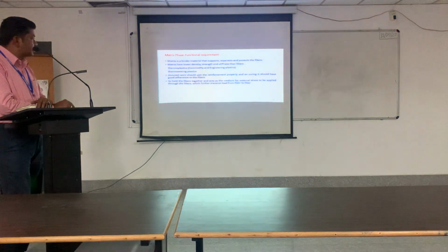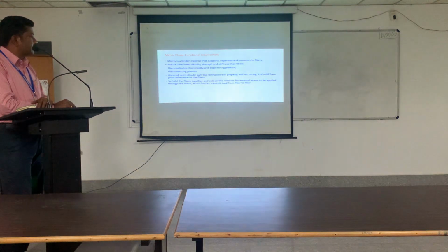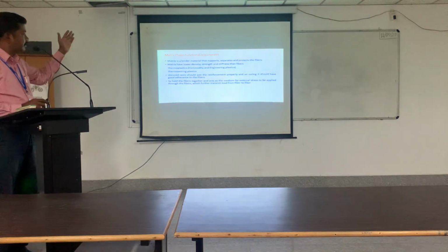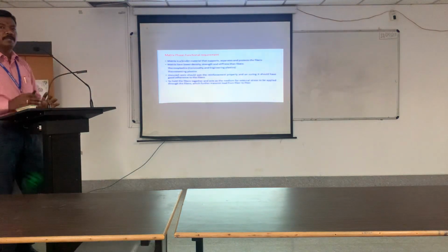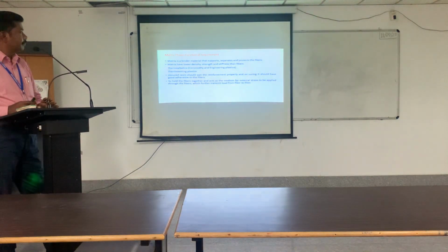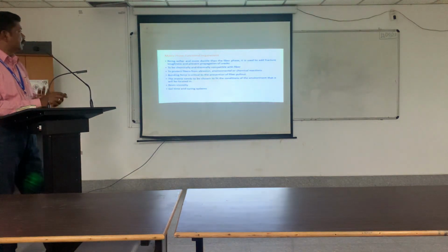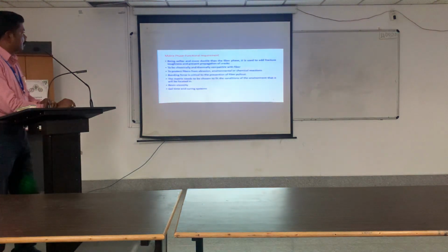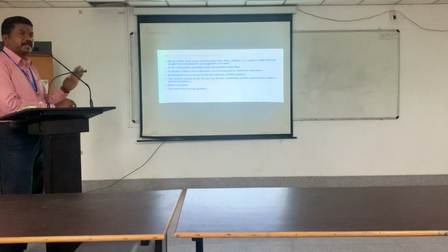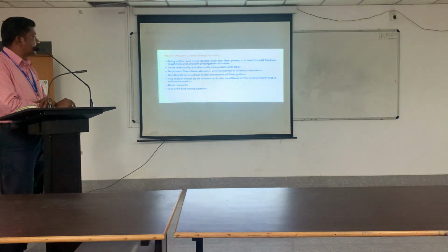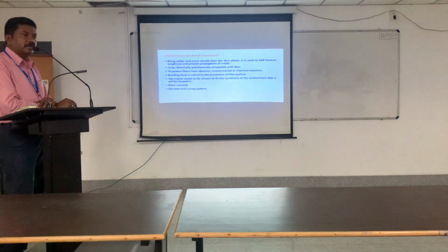To hold the fibers together and act as the medium for external stress to be applied through the fibers, which further transfers load from fiber to fiber. That is the combination of the first two points. It holds the fibers in the same direction and it will transfer the load from one fiber to another. In general, matrix material is the softer material. Matrix is softer and more ductile than the reinforcement.